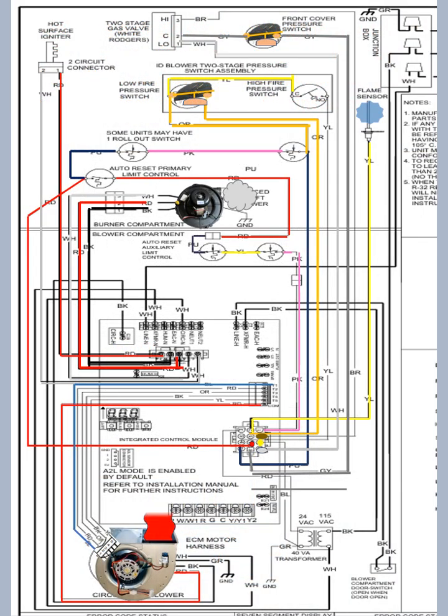The inducer motor is enabled at high speed, closing the second stage pressure switch and allowing the 24 volts to travel down the yellow pin 9 wire to pin 9 on the 12-pin connector, confirming the second stage pressure switch has closed. This will energize the high fire stage of the gas valve, and the second stage gas heat speed of the indoor blower motor is energized as well.